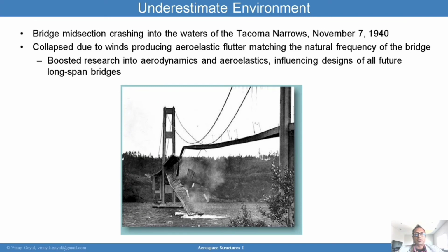And so it's important to ensure that the loading condition forcing frequencies do not line up with the natural frequencies of the structures. Otherwise, you could have a resonant condition that increases the loads quite significantly.